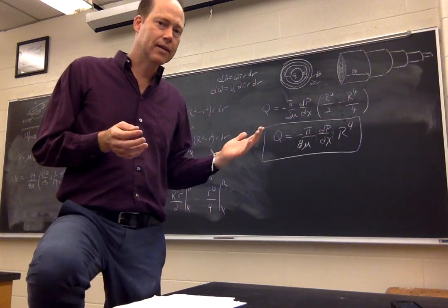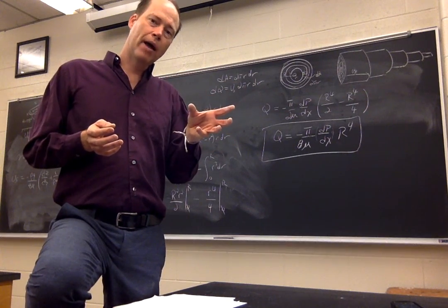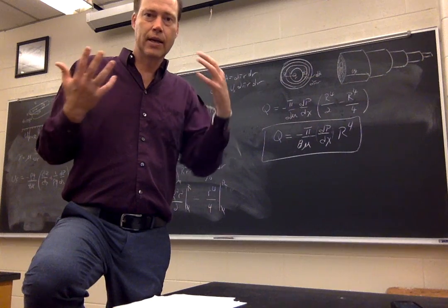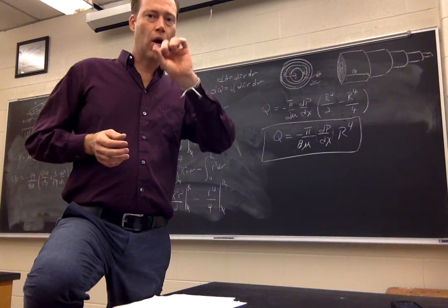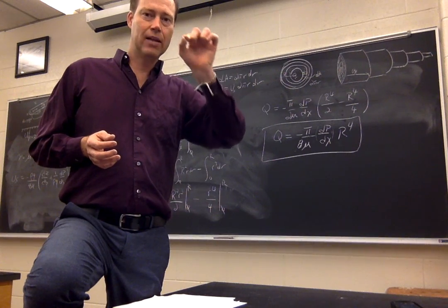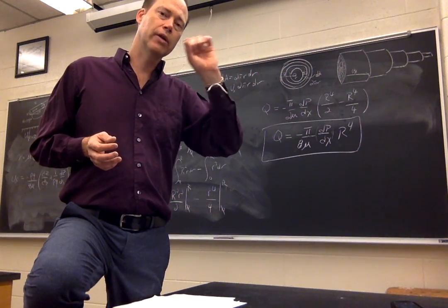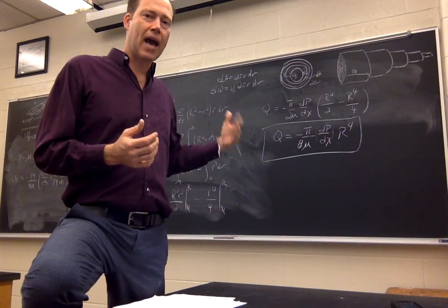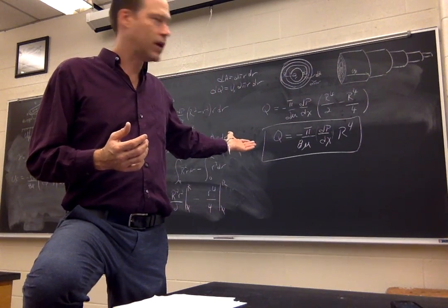In all cases, that really helps us understand the mechanics of how water moves. And we can even take this to a more microscopic level. Inside of, let's say, a sandstone aquifer, there are stream tubes in between all of the grains that connect the pore spaces, and those stream tubes, in a theoretical construct, behave similar to Poiseuille's equation.